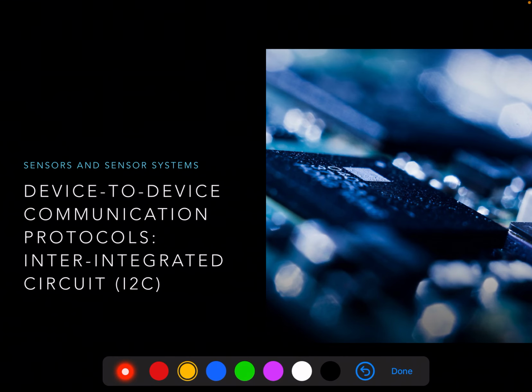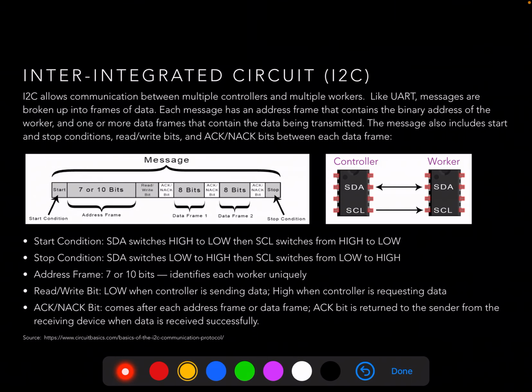Today's mini lecture is on a form of device-to-device communication protocol called the Inter-Integrated Circuit Protocol, or I2C. The I2C protocol allows communication between multiple controllers and multiple workers. In a sensing system, this likely means multiple microcontrollers talking to multiple sensors.